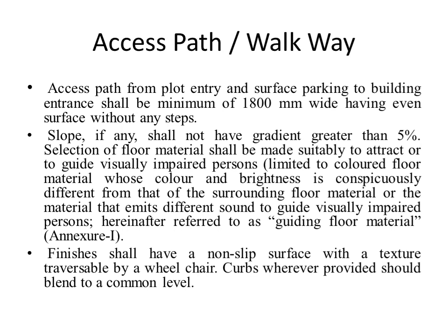Selection of floor material shall be made suitably to attract or to guide visually impaired persons, limited to colored floor material, whose color and brightness is conspicuously different from that of surrounding floor material, or the material that emits different sounds to guide visually impaired persons, hereinafter referred to as guiding floor material, which are given in the Annexure 1. The finishes shall have a non-slip surface with a texture traversable by a wheelchair. Curves, wherever provided, should blend to a common level.